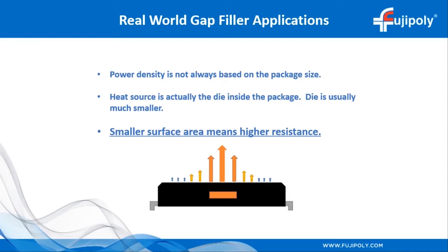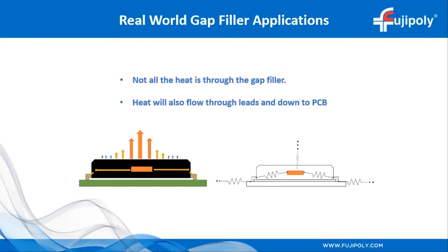Let's say we assume 10 watts of heat on a 1-inch square lid, but if 9 of those watts are primarily distributed towards the center and you only have 1 watt on the outer 1/4 inch perimeter, then the material really isn't doing much. This might create the need for a higher performing pad, or a designer might realize that they can undersize the pad and save some money on the cost, and still get away with using the same material.